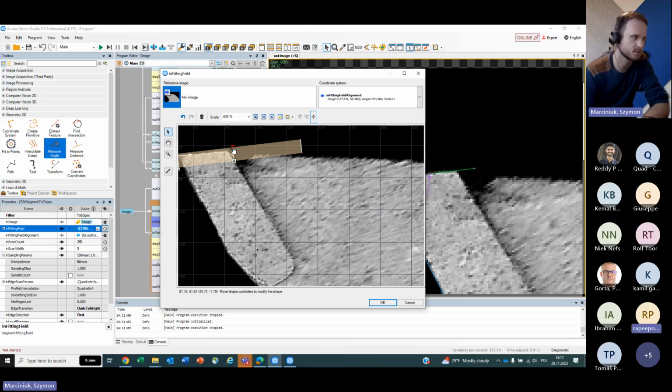We don't have that directly in our software, but you can use communication cards that have this option. You communicate, for example, via TCP/IP with the communication card, and the communication card is set to communicate, for example, with a robot via Profinet. That's how it's done. And TCP/IP communication is very important, and we will cover it during tomorrow's training because it's just the most widely used and can solve the majority of applications, I guess.